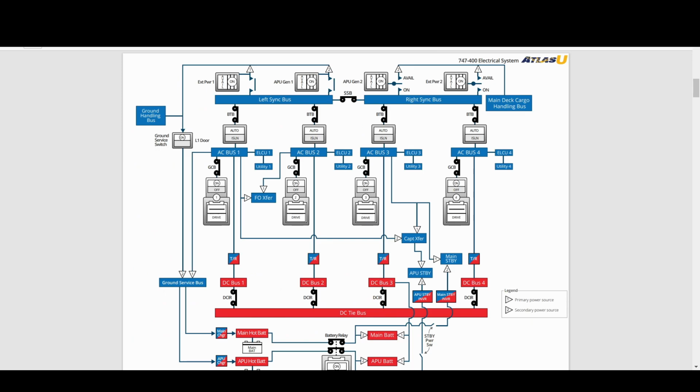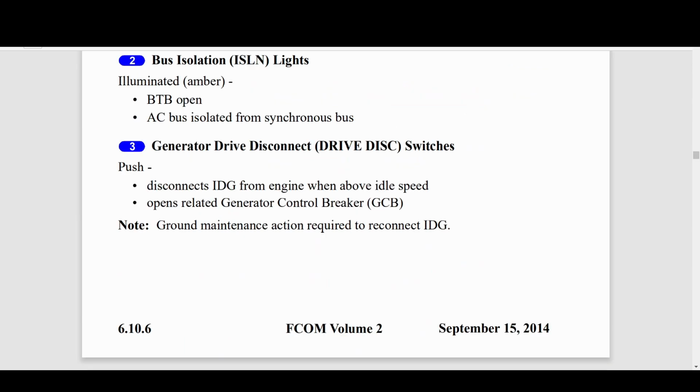What happens when you push a generator drive disconnect switch? Disconnects integrated drive generator from engine when above idle speed. Opens related generator control breaker.